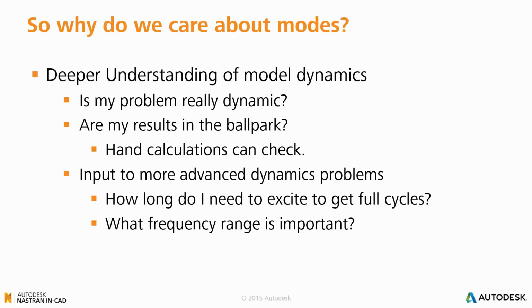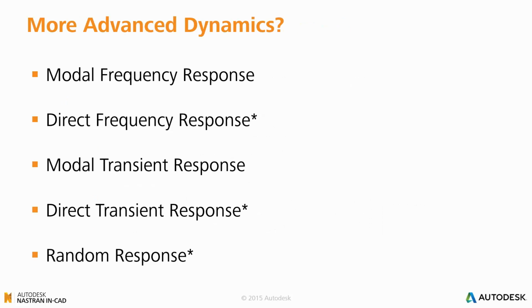But it's also a lead-in to some more advanced dynamics problems. So we could run, say, a modal analysis initially, or a normal modes analysis, but then run subsequent analysis to look for true stress, true displacement. And it's also highlighting the frequency range of our parts where we might have critical frequencies that we want to try and avoid, or adjust the geometry to try and shift those frequencies away from. If you want to run more advanced dynamic analysis, then we can look at other analysis types like modal frequency response or modal transient response, and there's a whole range of different response analysis types that we can run for dynamic problems.